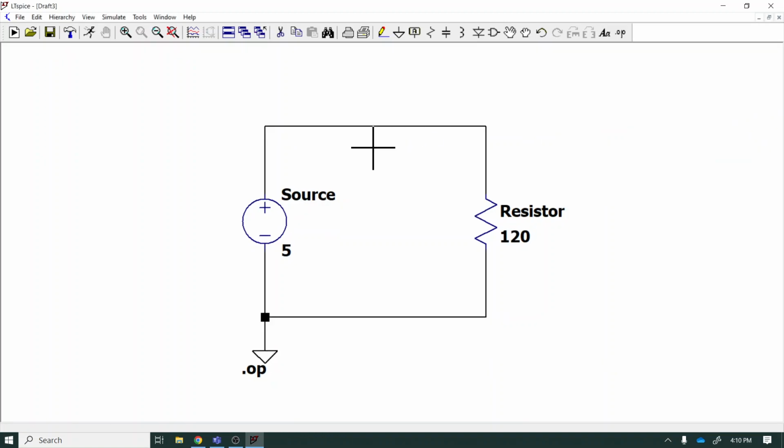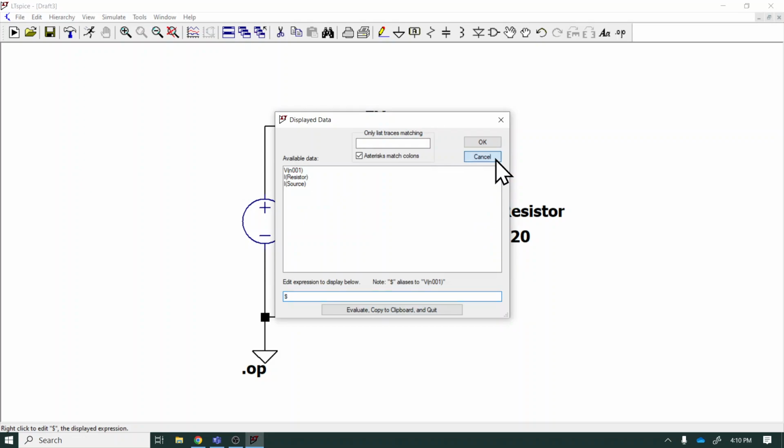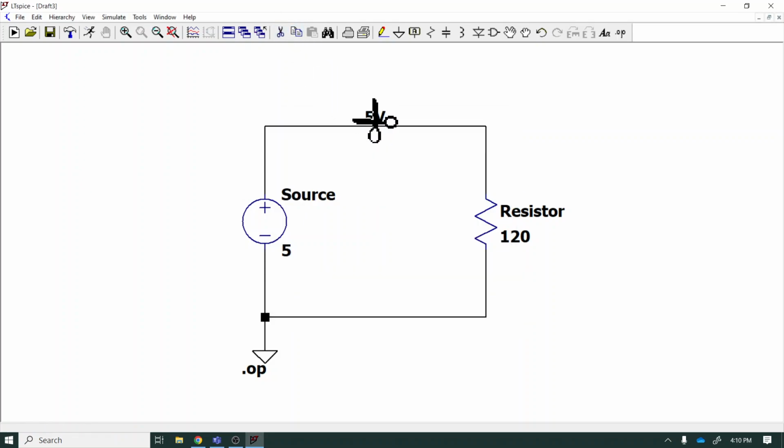As you look around the circuit after you've cleared it, if you look down in the bottom left-hand corner of the window, it says this is node N001, DC operating point, V(N001) equals 5 volts. So this is what we call the node or the net.